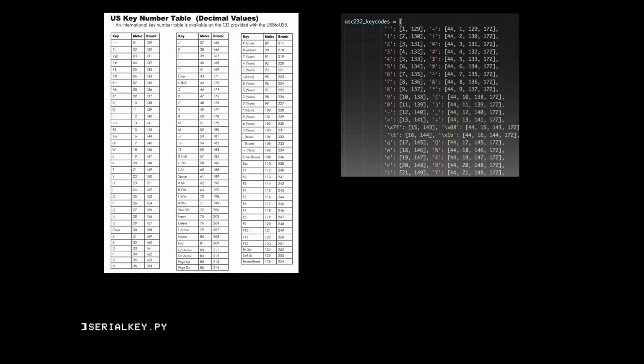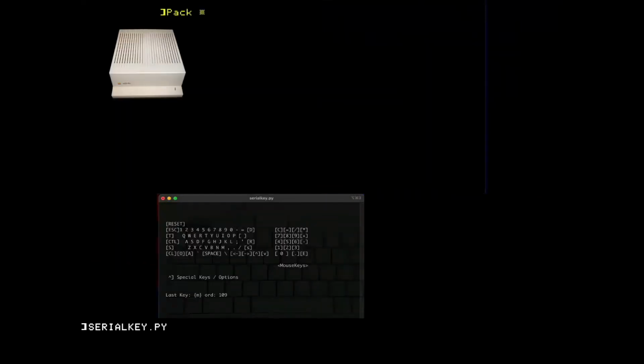The USB to USB works by receiving serial commands for key down and key up codes, and sends them over USB as if it were a connected keyboard. I wrote a simple program in Python to read keyboard keys and send them to the device. It has some limitations, namely with how modifier keys are entered, but I had originally intended for it to be accessed over Telnet or SSH, and thought it might be nice to visually know which keys were being triggered.